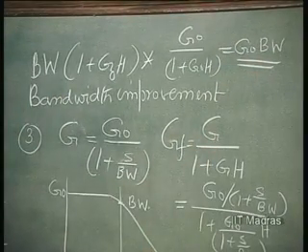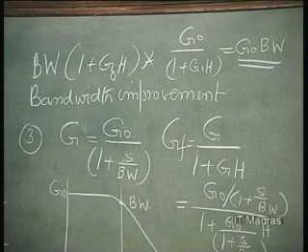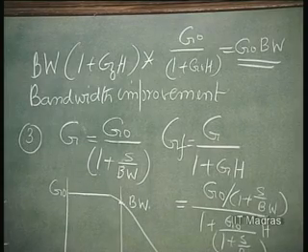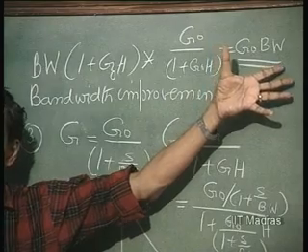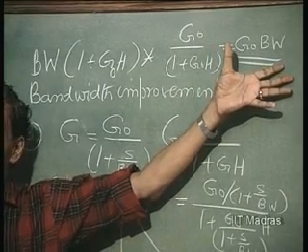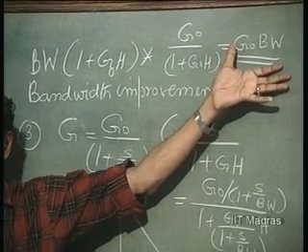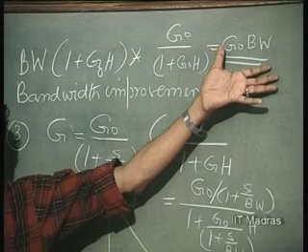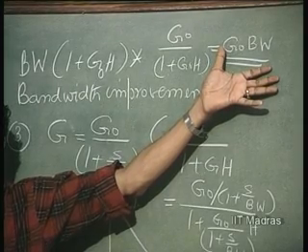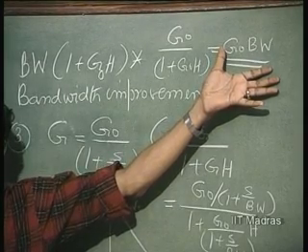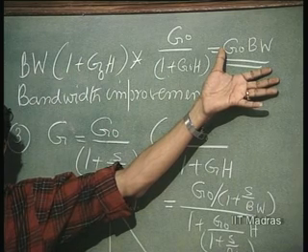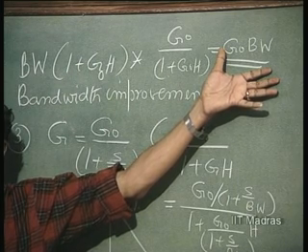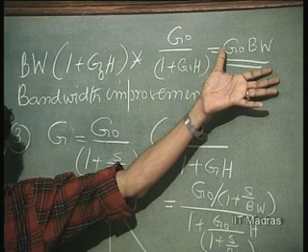So, this is another important conclusion in negative feedback. The gain into bandwidth remains always a constant. That means, if I have an open loop amplifier with 1 megahertz bandwidth having a gain of 1, that will have a bandwidth of 100 kilohertz when it has a gain of 10.